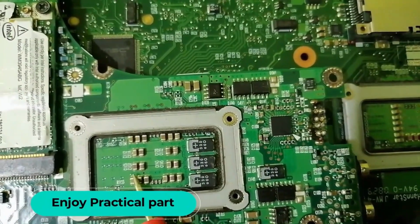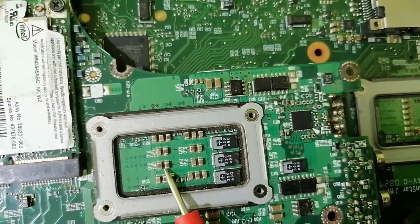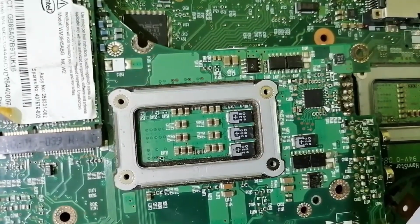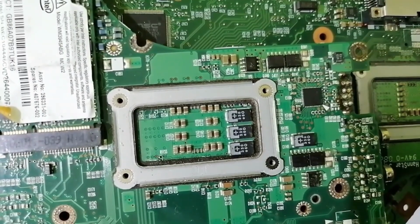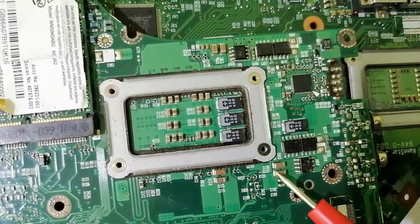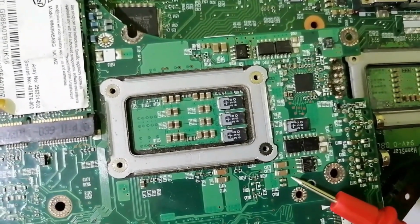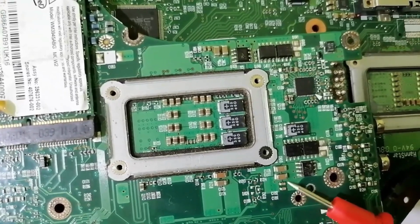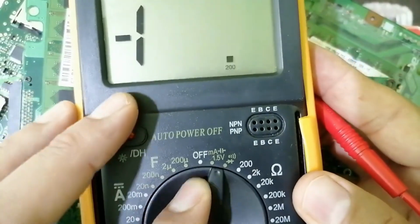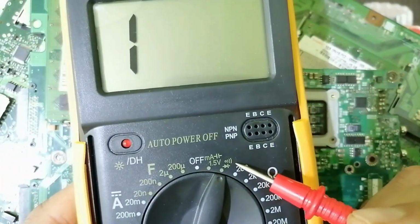So as you can see over here, these are the ceramic capacitors that we are going to test using the multimeter. You can find many types of ceramic capacitors in laptop motherboards and computer motherboards. For example, you can find this kind of big ceramic capacitors. Also here we have other ceramic capacitors, as you can see. To test the ceramic capacitors, we are going to use the continuity option.